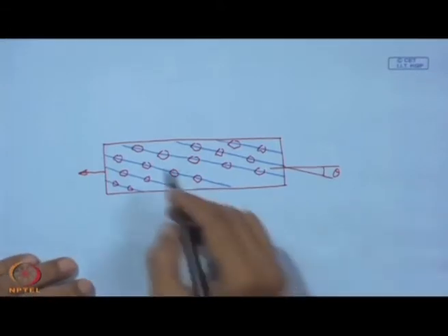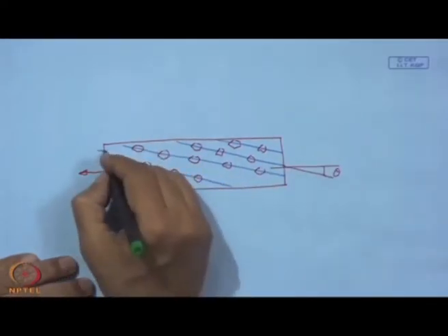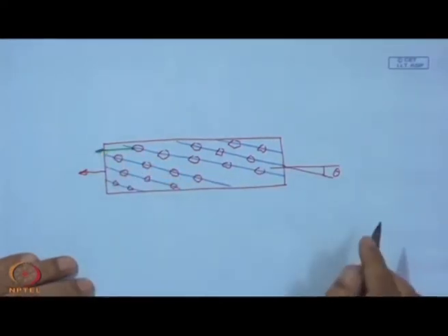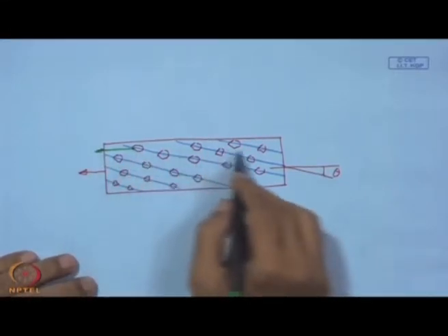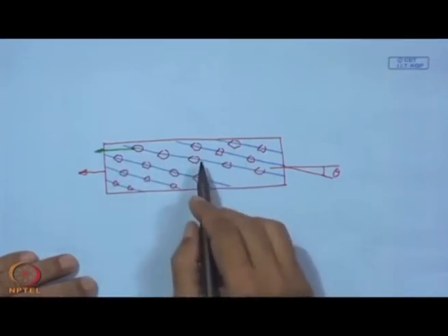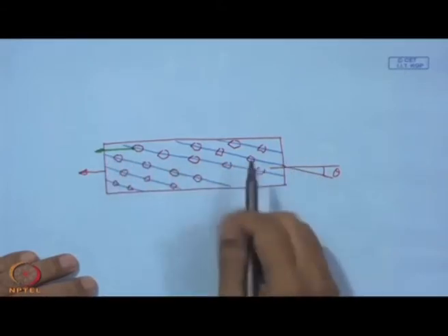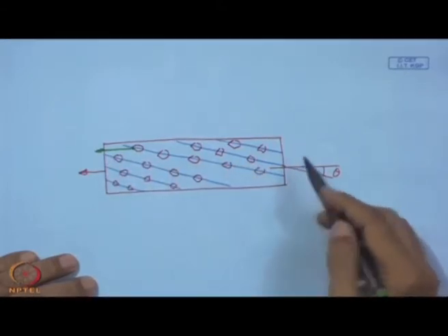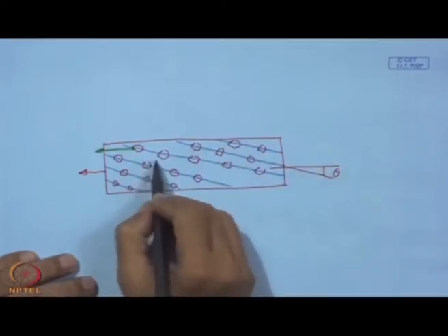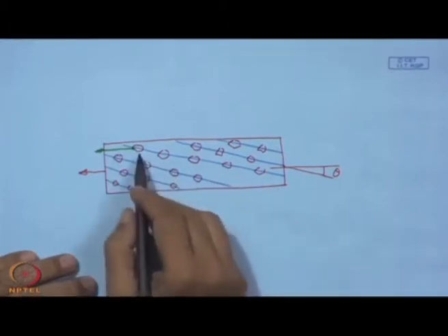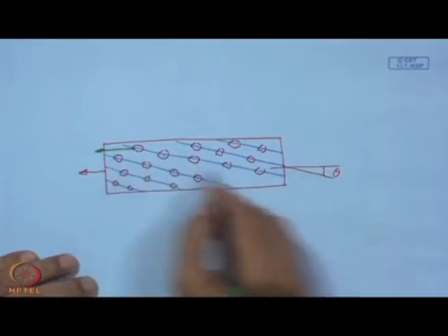Each grit has its cutting action in this direction, but in the direction of motion we get more number of lines. Just by having this angle of obliquity, we have so many grits, not just along the helix line but slightly oblique to it, and that is why for each cutting point we have more scratch marks.